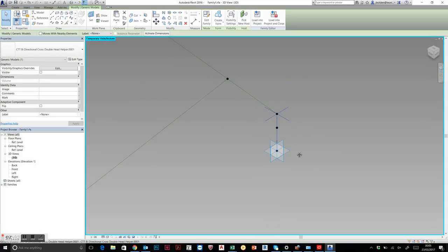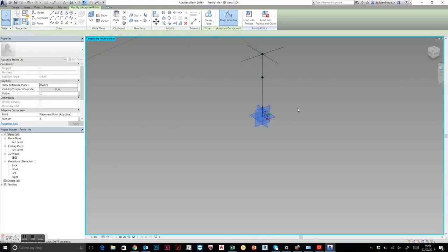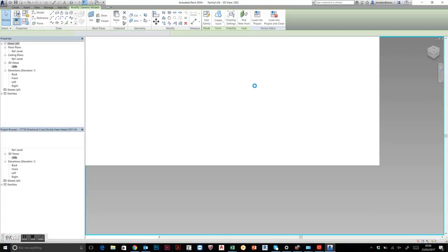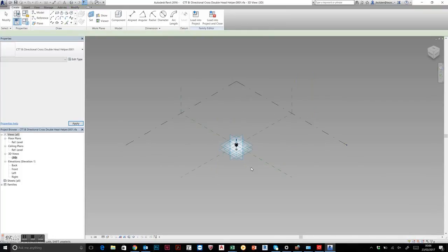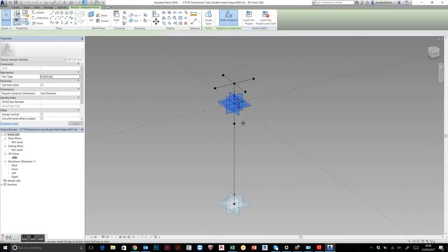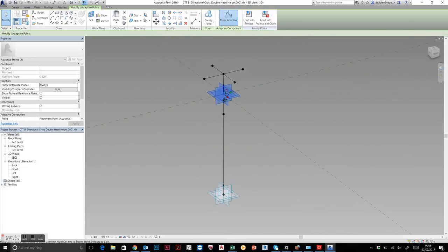Revit has a terrible tendency of not knowing which way is up. By making a family that can only reside as up in a given location, that makes life a little easier. I'll just come into that so you can see it. Again, adaptive families are your friend. You should have tried modeling in Revit before adaptive families. Jeez. This is essentially a line.